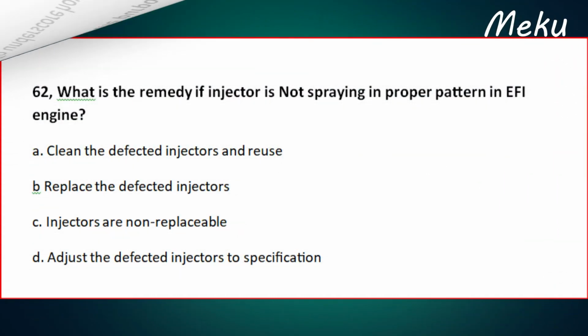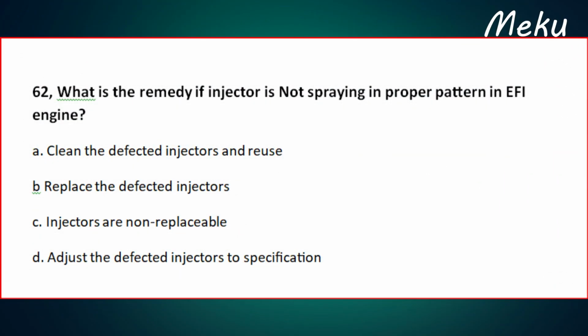62. What is the remedy if injector is not spraying in proper pattern in EFI engine? A. Clean the defected injectors and reuse. B. Replace the defected injectors. C. Injectors are non-replaceable. D. Adjust the defected injectors to specification.